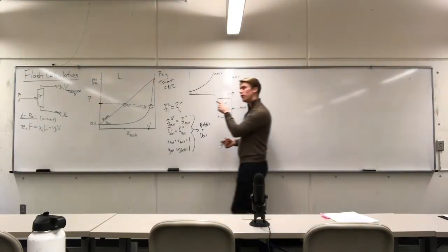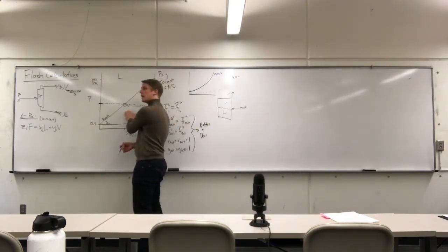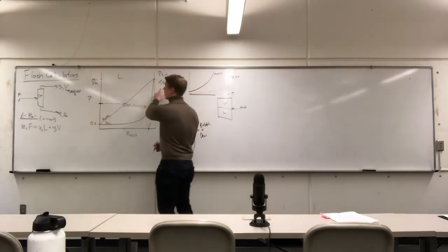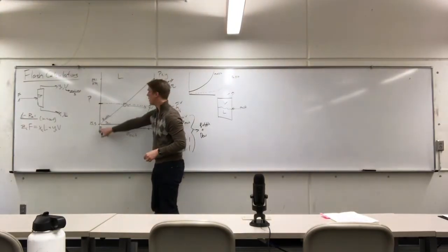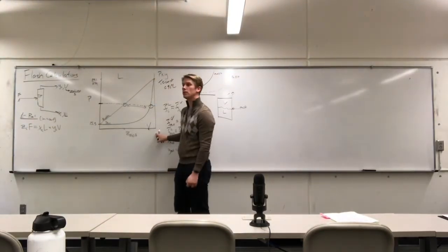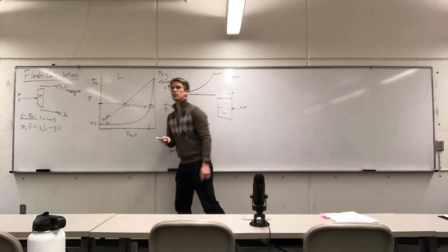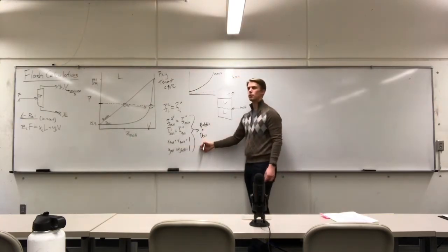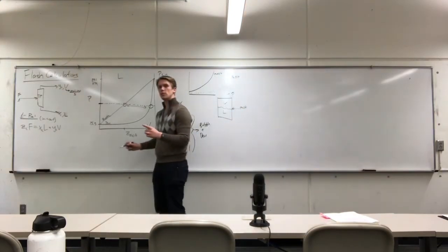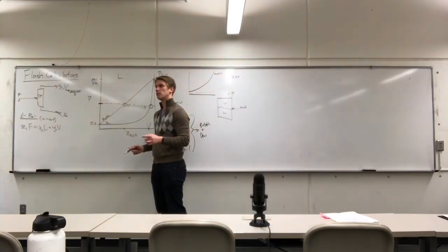So in order to generate a phase diagram, I don't actually have to consider all of the possible conditions of temperature, all of the possible conditions of pressure, and all of the possible conditions of composition. Because there are only two lines that satisfy the multi-phase, multi-component equilibrium. So instead, we do something called a dew and a bubble calculation.